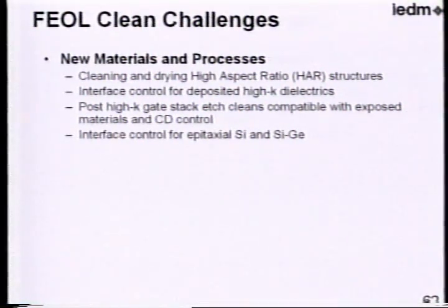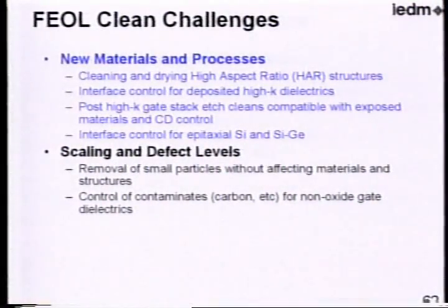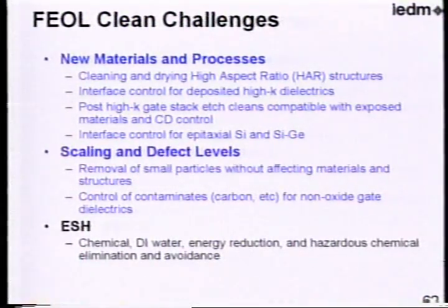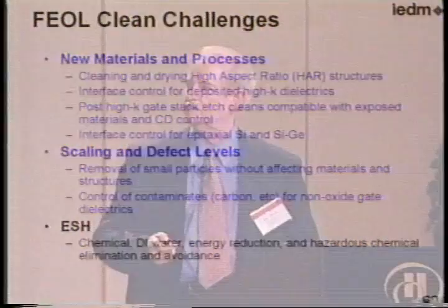And cleaning challenges, I didn't even get into this, but there are all kinds of materials. All of these have their own cleaning challenges inherent to them. We're introducing all these new materials potentially in parallel, and the number of permutations, the ways you can do things, is just unbelievable. Scaling and defect levels are also a concern; you've talked about contamination control. Not only is it particles, but the materials introduce a lot of different kinds of contamination issues, such as precursors and so forth, and the high-K materials. And of course, ESH is always a concern.